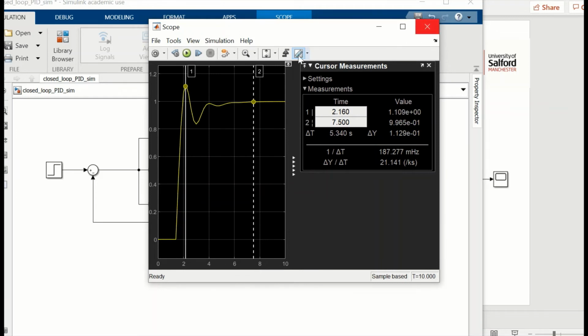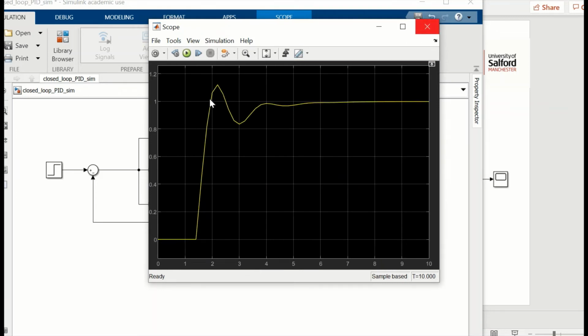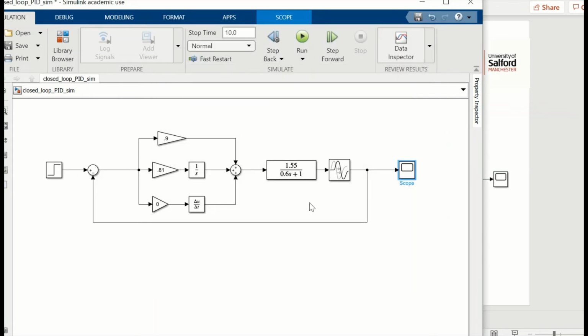So Ziegler-Nichols is not bad, but it's not as nicely rounded a curve, is it? But it's because it's got this bit of undershoot here. But it wouldn't be a bad set of gains to start off with. You could tune this arguably to get something quite good within a few minutes. So there's your Ziegler-Nichols gains.